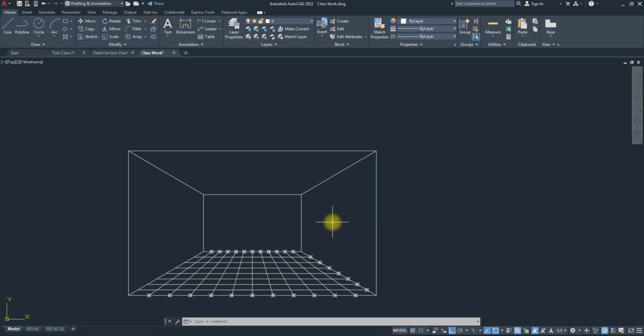So what we can do is let us continue working. You know that there's a pillar at the back, and if you look at it clearly, this wall goes all the way to there and pushes in. Okay? So we need to create that part of the wall. But the good thing here is that this subdivision will help us, because we've already done this subdivision, so we can pick one of these to use to simulate this end of this wall.